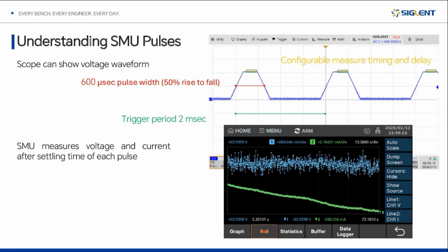You can adjust all those delays and timings, and offset them. You can even move the measurement to other parts of the pulse, depending upon what you want to see. That customizability allows you to think more clearly about what you're trying to measure, what accuracy you need, and what state you want the device in when it's being measured and ultimately analyzed.